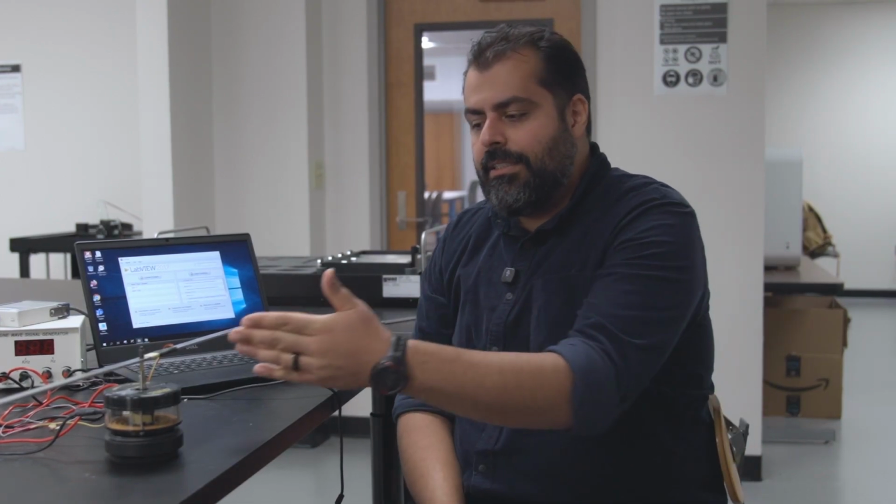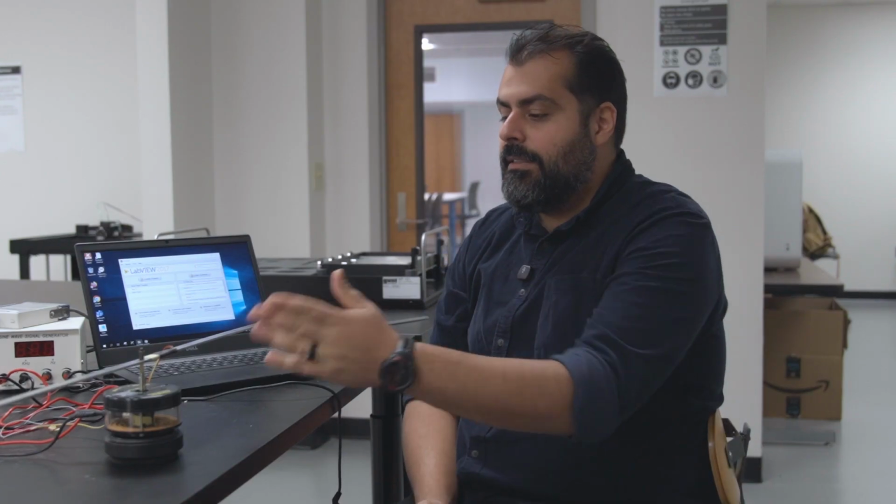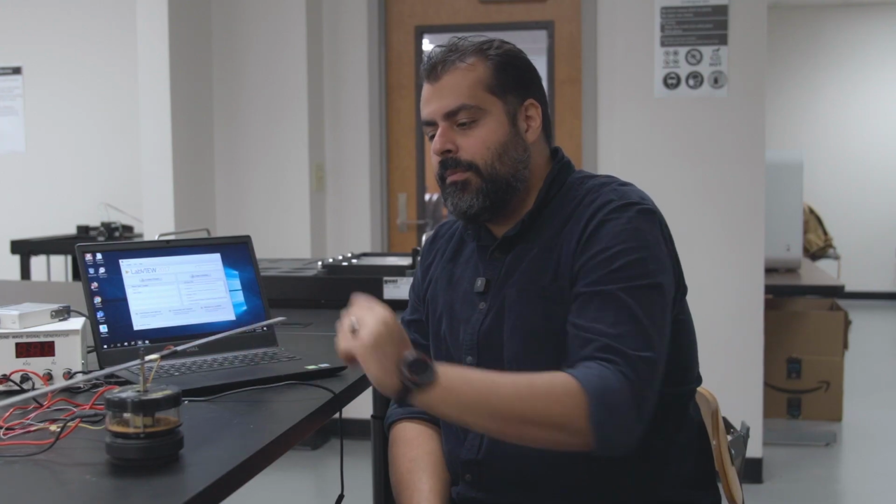And we are going to use a strain gauge, which you are already familiar with. You used the strain gauge in lab 1 to calculate the natural frequency. This strain gauge is connected to our computer, so we are going to create a LabVIEW program to measure the strain of the beam at this specific location.